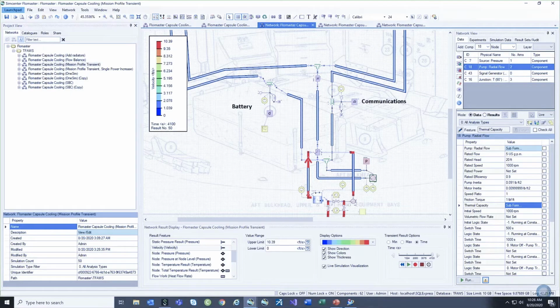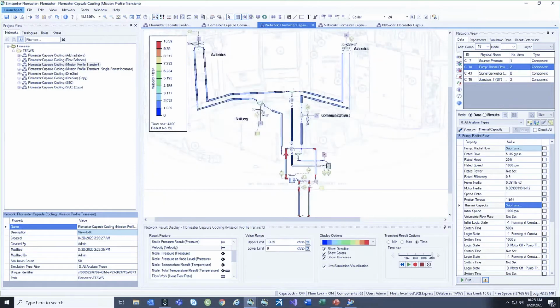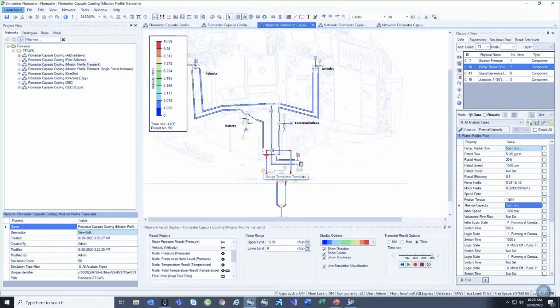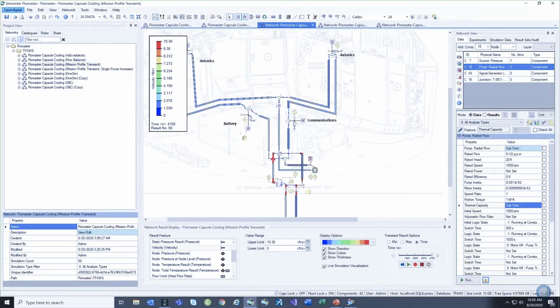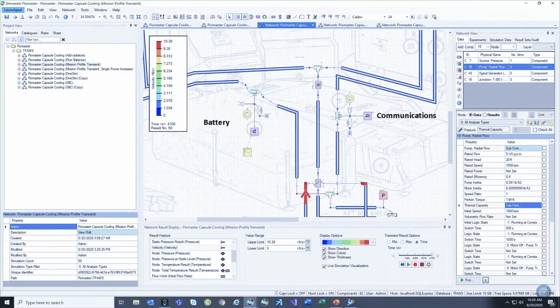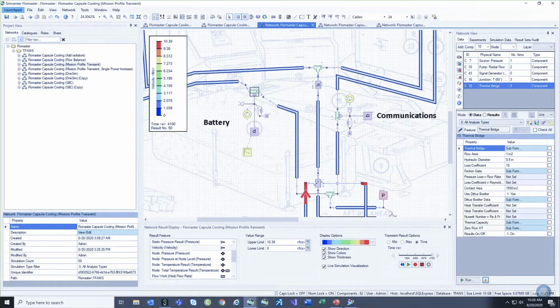When that spikes up, we're not going up to infinity because we did leave this backup heat transfer mechanism, right? We're modeling the convection and the radiation out to ambient air as well as the liquid cooling. So it's not necessarily a dire situation, but it is a problem, right? We want to make sure we design for redundancy and have another heat transfer mechanism should that pump fail. Maybe we have 2 parallel pumps. We could test that as well. Right? So that's the transient analysis.